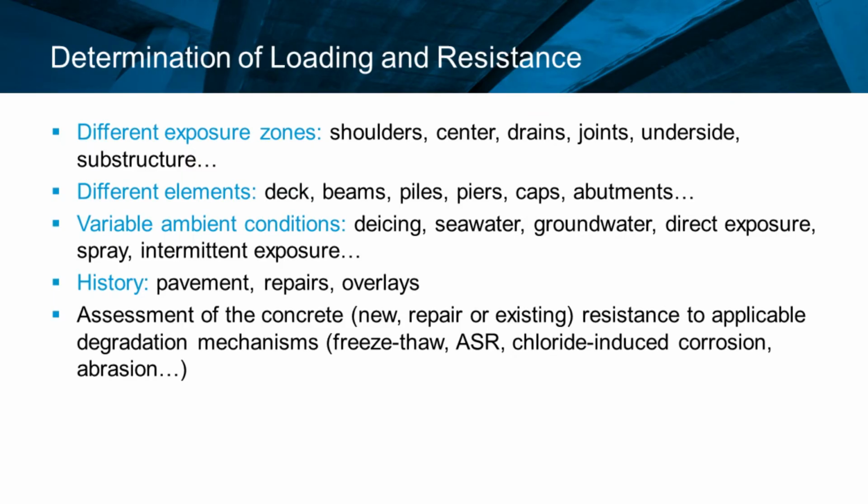And regarding the concrete itself, I just mentioned that we can act on different parameters to optimize the concrete mix, either a repair mix or a new mix, to influence the resistance to freeze-thaw, the resistance to cracking, volumetric change, chloride penetration, chemical attack. So if we know what the concrete is exposed to, we can act on the parameters that are the most likely to influence directly the durability and the service life of a given element.